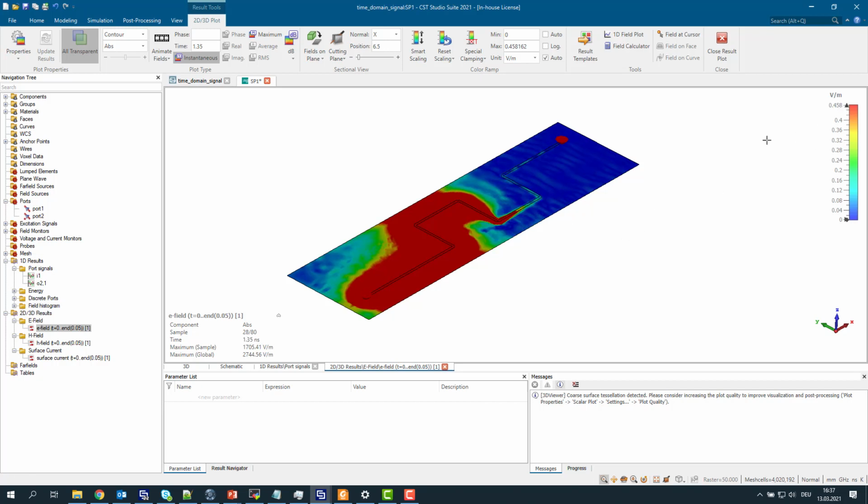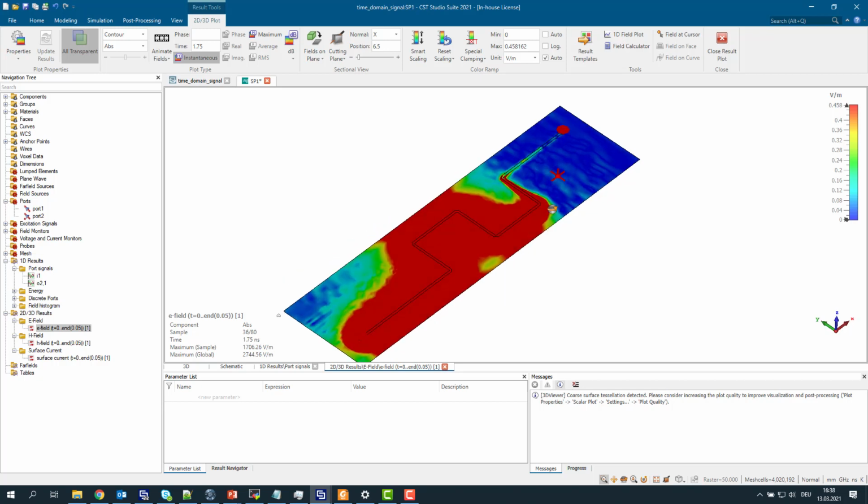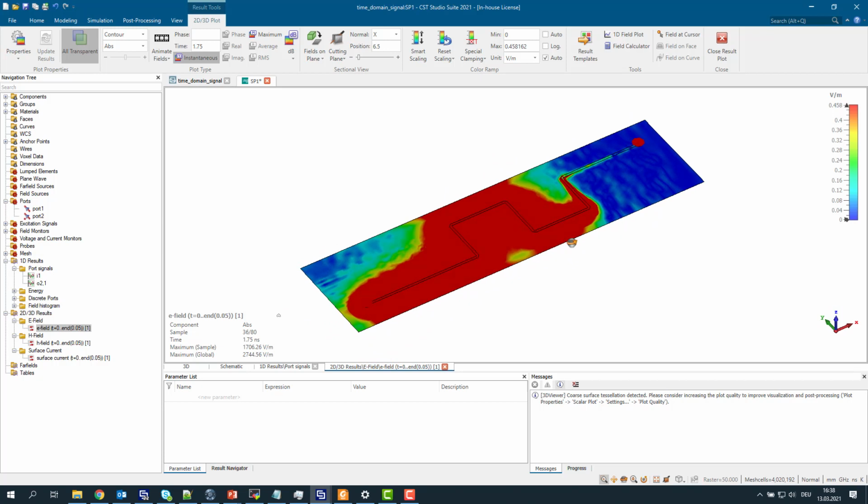Of course, that's a very small value. Think that there was 1000 volt per meter between the trace and the ground plane at the position of the signal trace. But nevertheless, the fields are there, and there are other applications where even this kind of small fields can make problems, for example in RF systems, where really small voltage values can lead to system degradation. So keep this in mind: it's always best to think about fields and Maxwell equations when looking at the propagation of signals on a PCB.